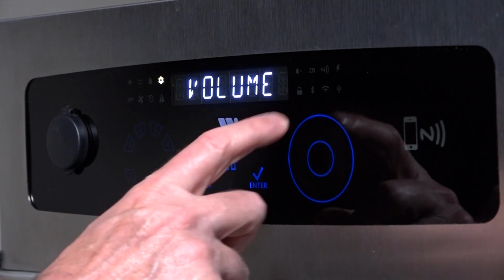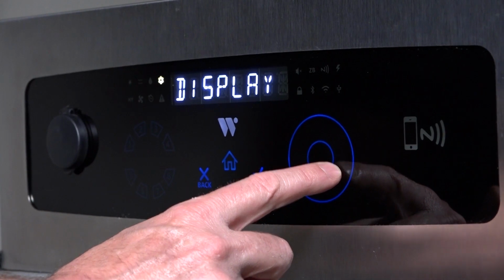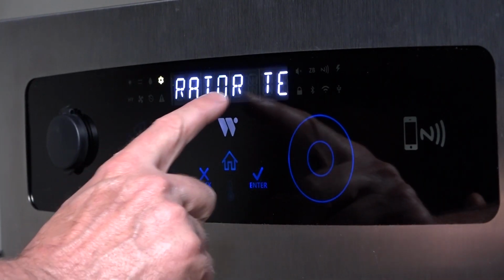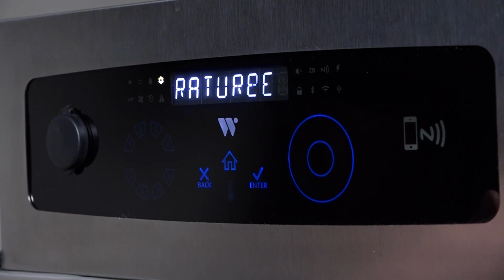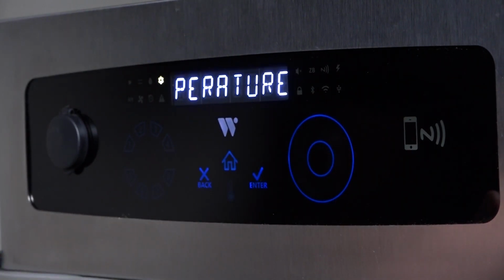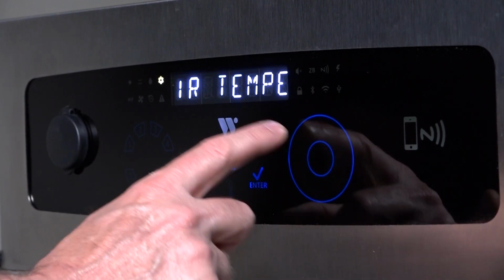Using the dial pad, scroll clockwise to the next setting submenu, which is Display. Press Enter. This menu allows you to have the air temperature or the water temperature displayed. Using the dial pad, scroll to select desired display and press Enter.